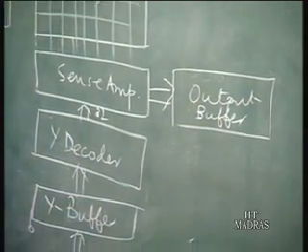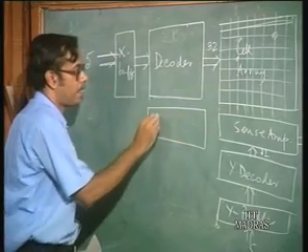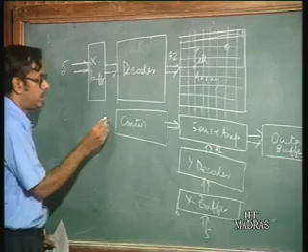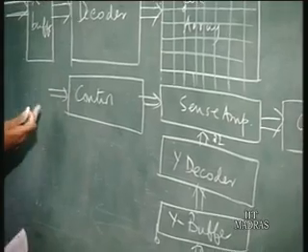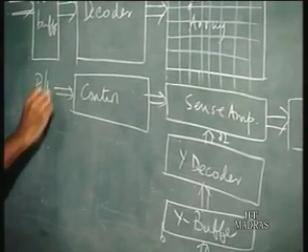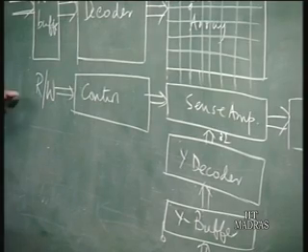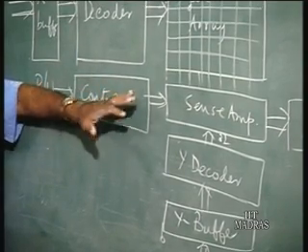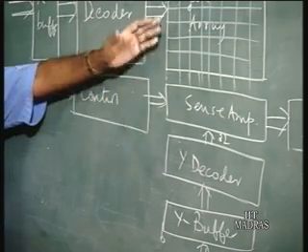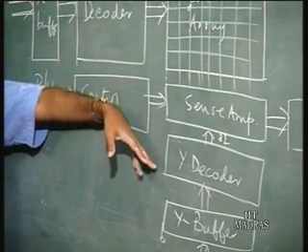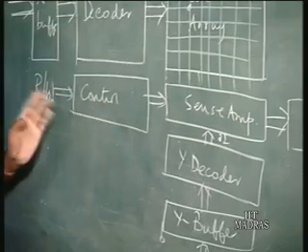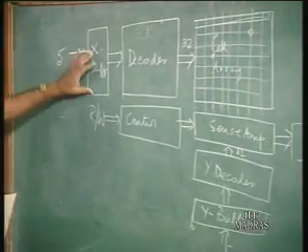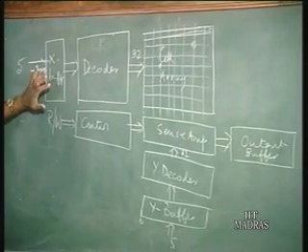And then you also have a control block, okay, which is fed to the sense amplifier, which gives information like whether you want to read or write and these sorts of information, okay. For each of them you have to generate the particular control signals which are going to drive all these different circuits, okay. So basically this is the block diagram of any memory, okay.